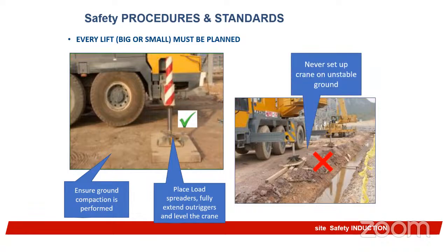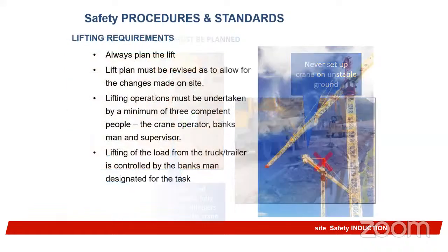Then never set up a crane on unstable ground. Don't set up your crane on grounds that are unstable. You can see this, sometimes we do this a lot. We'll put some planks under it to make it stable. This is not always advisable.